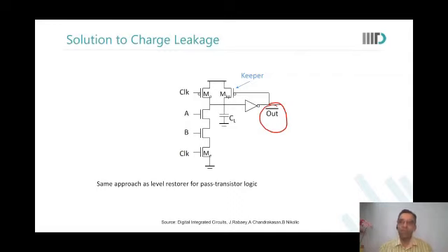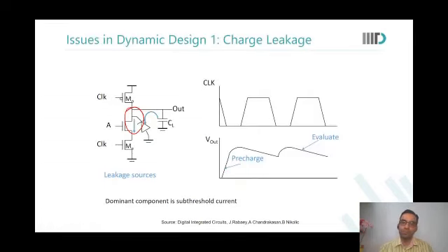Okay. Rajneesh, you have a question? Sir, can you move back one slide, sir? Sir, when the precharge is off, the output keeps leaking through this reverse diode. But when we turn the precharge on, this diode is still reverse biased, so it should leak then also, sir. Yes, but then there's a stack effect also coming, na?